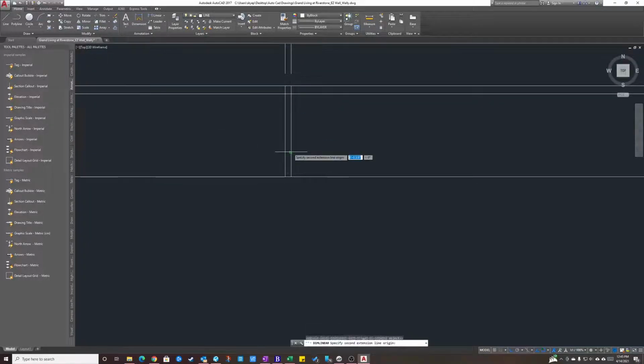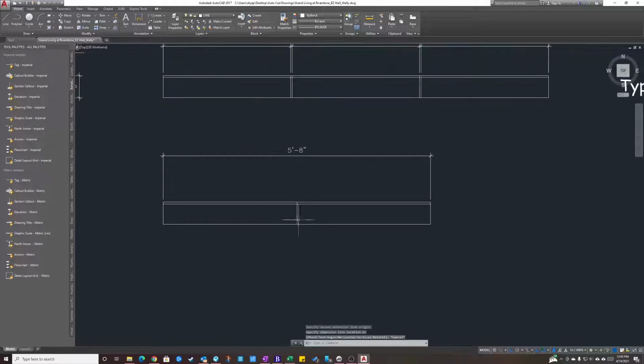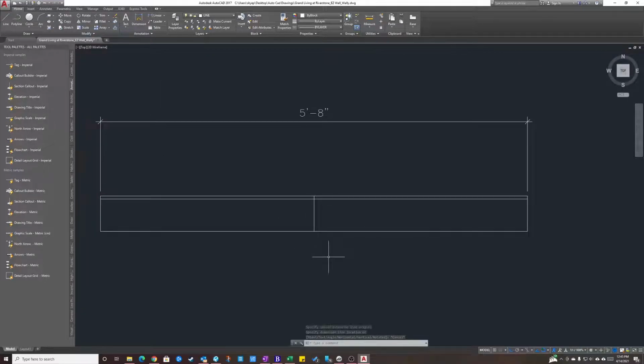You see how the space is 3/8 of an inch? Well, how do we get 3/8 of an inch here? Okay, well, easy. 3/8 of an inch divided by 2 is what? 3/16 of an inch. So it's 3/16 of an inch on either side. So in order to get a 3/8 joint perfectly in the middle, we have to reduce the stone by 3/16. 3/16 in decimals is 0.1875. It's a very important dimension. You'll be using it a lot.